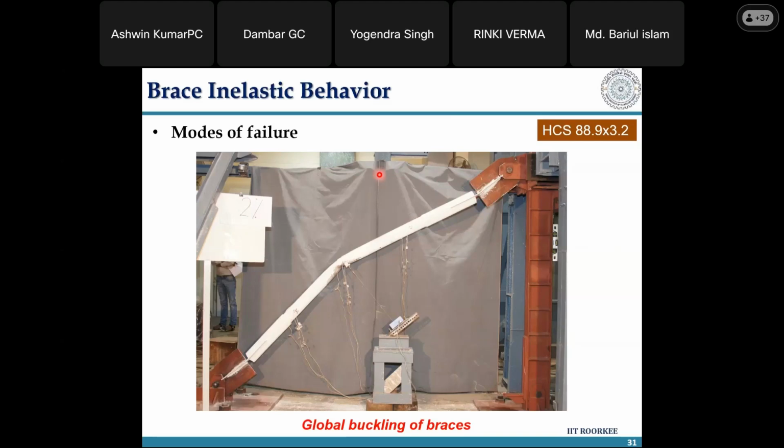Buckling restraint braces are much better than CBF systems because they are meant not to buckle. I mean, they give equal energy dissipation in tension and compression cycles. There is a core element, but in a buckling restraint brace, what we do is we encase the inner core element. Let's say this is a brace here, which is buckling globally, right? If I give a protective coating or a shield around it, such that the buckling of the member is, I'll tell you the concept behind it.